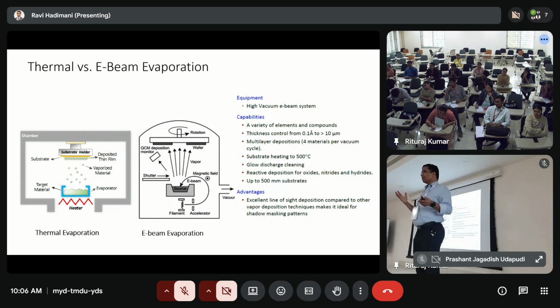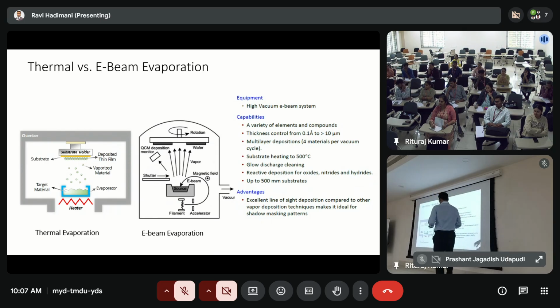What is the property of quartz? Yeah, it vibrates when you apply an AC field, and if it is vibrating, then it generates an AC field, or if you apply static pressure, it generates DC voltage. If you apply DC voltage, it changes its size. So now, can you think how it can monitor the thickness? It can tell you what the thickness is here.